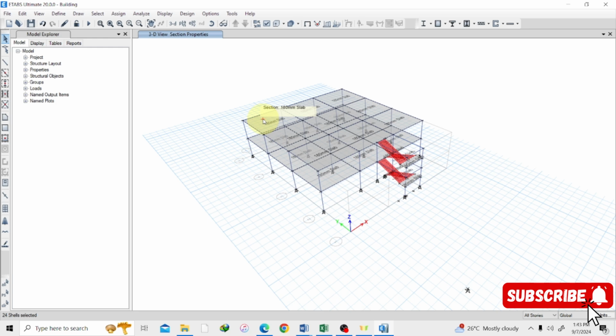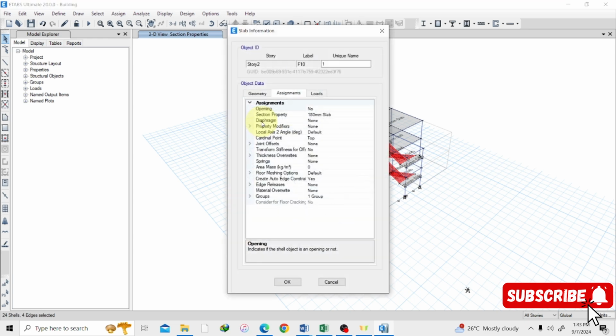So I'm going to show you that ETABS already has its default mesh. I'm just going to right click on this slab, and look here, we have floor meshing options. It's default, it's not none. If it were none, that would mean this slab has not been meshed, but it's default. That means the ETABS app has its own default meshing properties that it gives the slab, but we don't want to use these defaults. We want to use our own mesh that we create.